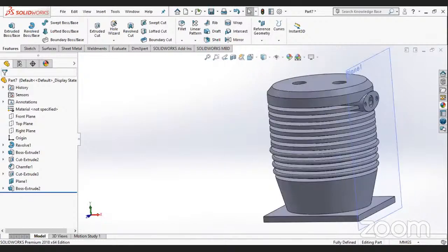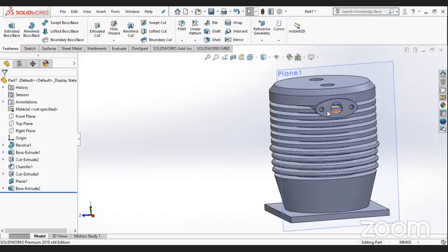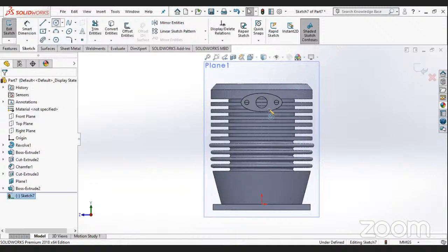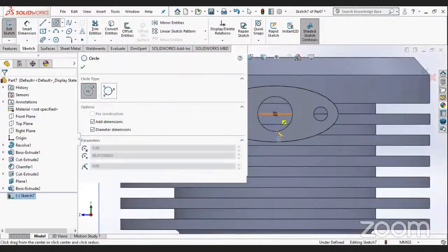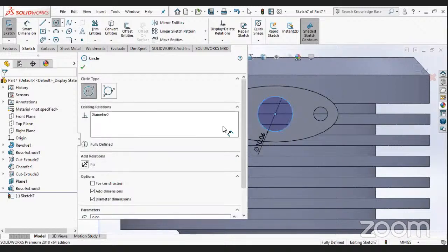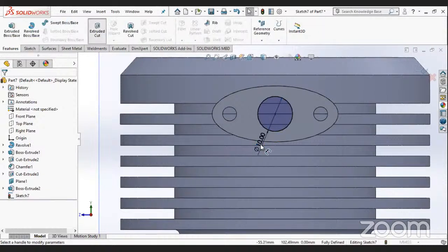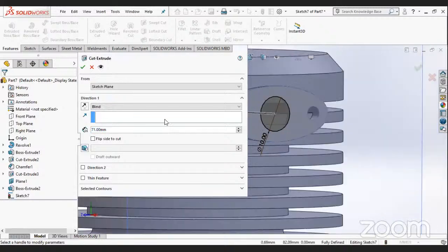Let's see what it is also on the other side as well. And there is a pure hole till that. So we can just quickly extrude, cut the inner hole which we have here. Just sketch on this surface. Make the same 10 mm circle here. And just quickly extrude, cut it to the next. We'll get a hole to that.